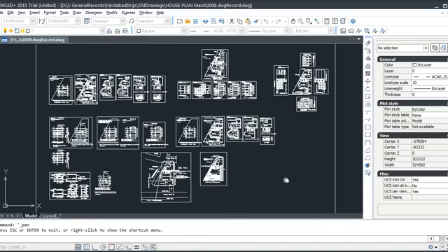Then we pour it, not more than 400 mm in one go, and we vibrate that, and then we start work of columns and other work, and we check setting outs, we check dimension, we check plumb line, and we check this exactly in the same setting out line. Plumb is checked on at least two sides, and all four dimensions are checked, so these columns remain in line, and also remain truly vertical.